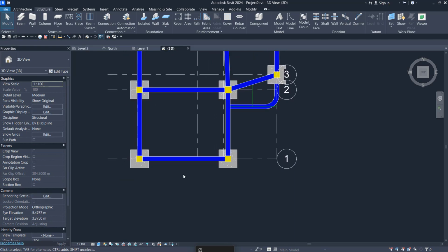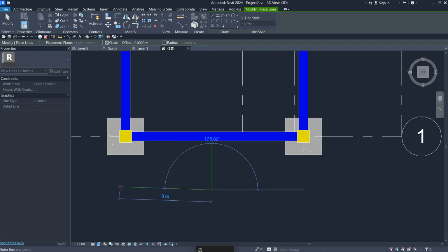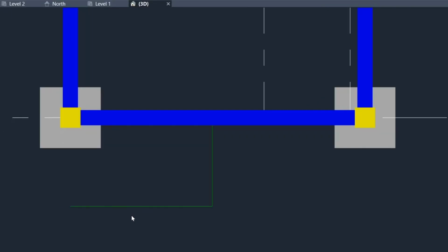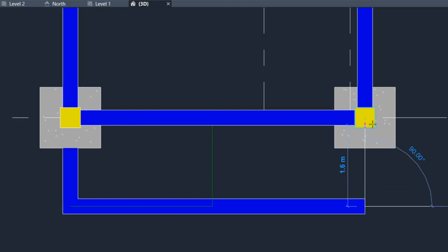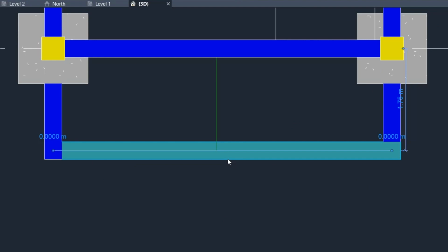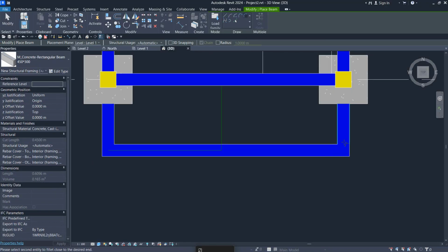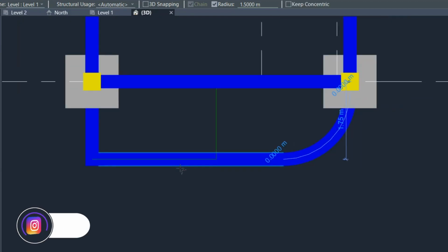We can do the same thing in here. Let's press LI for line, and let's create a 160 in here and in here, and that's great. And now let's create similar from this one, and let's create a beam in here, and let's create one in here. I want to do the same thing or same fillet in here too. So let's press CS on this one and use fillet arc. So let's put it on radius and 150, and let's select this one and this one.